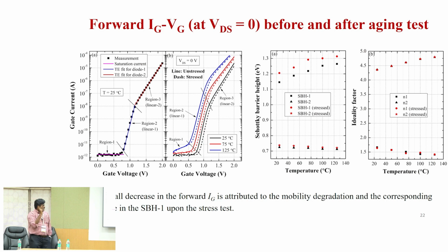It means that your Schottky contact, your gate semiconductor contact, is having a non-homogeneous barrier height. Your metal semiconductor interface is having two barrier heights. If you are having this kind of two barrier heights, it's difficult to analyze. One barrier height is larger, one barrier height is lower.